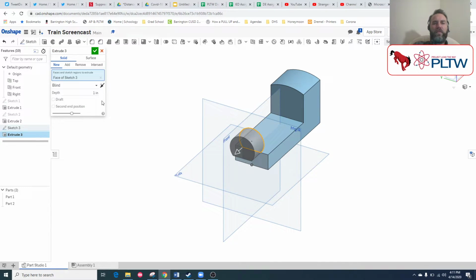Right now, as it's set to extrude off the front here, those two extrusions aren't meeting in any way, and so it's kind of like creating two different parts. And you can see down here we've got part 1 and part 2 inside of my part studio. I want one single part. So when I send it the other way, I think that just starts to take care of itself. It hasn't yet, but it will. And so I'm going to say just to next.